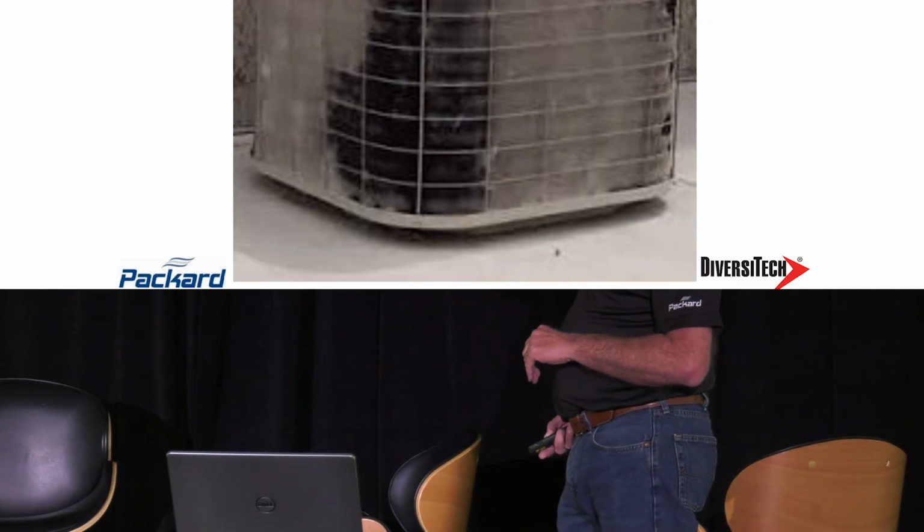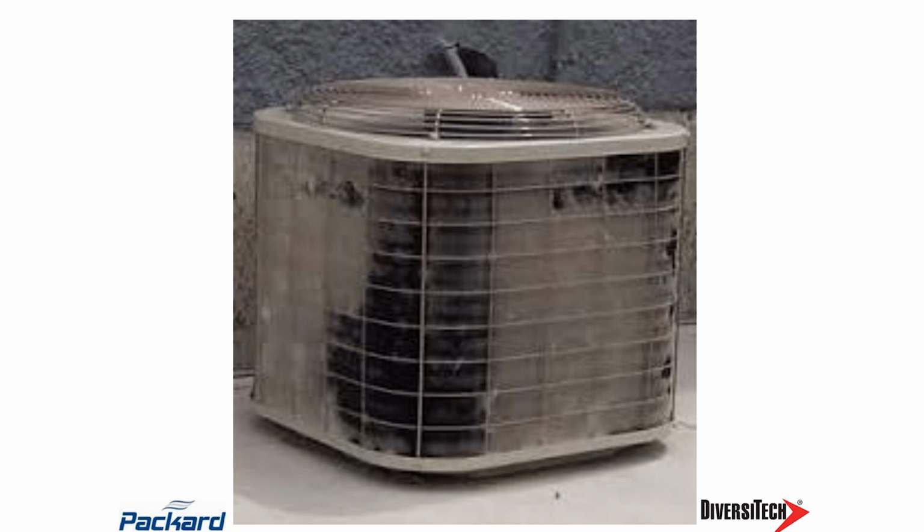That stuff happens. If somebody has a deck built over their condensing unit, and if they have a trap door on that deck, if you were to measure the amps of the motor with the trap door on, with the trap door off, that's going to affect that static pressure, which is going to affect the load, which is going to affect the amps on that motor. So those things all affect static pressure and the load that I see on that. How about that? Anybody ever run into anything like that?